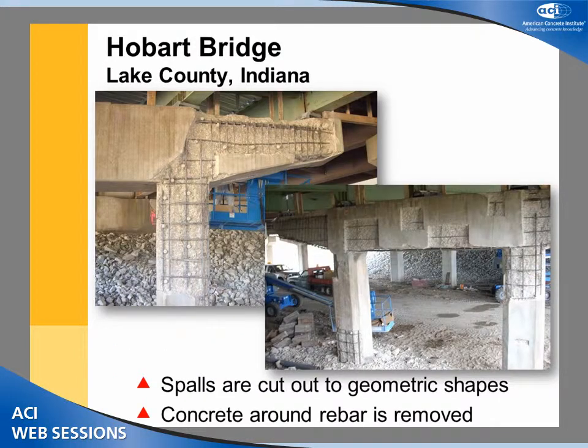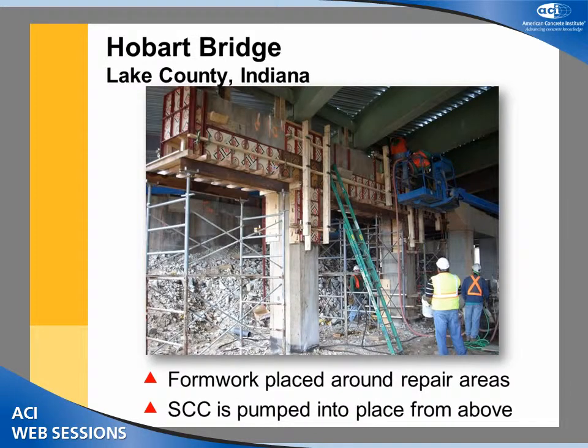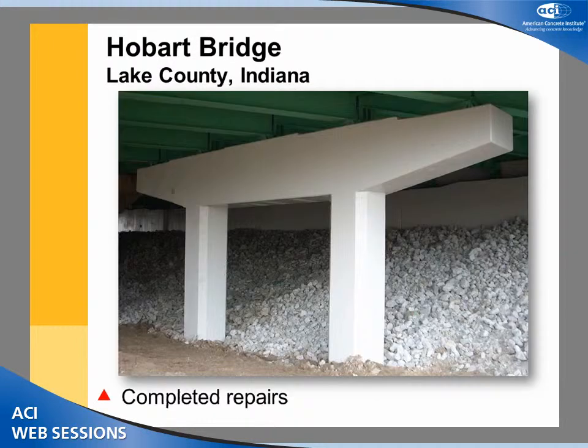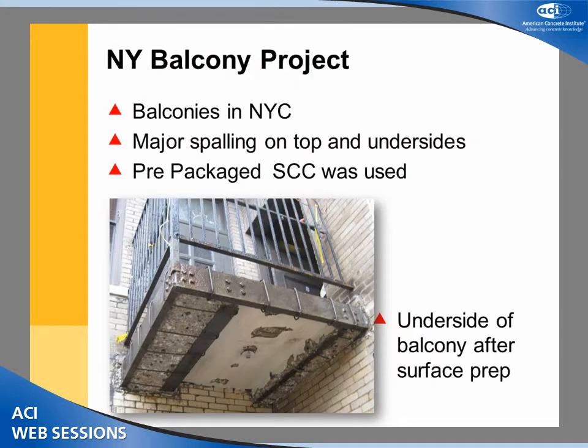You can see the extent of damage in these structures. You can probably do this with conventional 8-9-inch slump concrete, but getting it done with an SCC makes it a lot easier for the contractor, and you actually end up getting a much more durable product. This is the section that's being formed up, and you get the lift, and the guys are just pouring the material right from the lift. This is how the structure looked once it's all said and done.